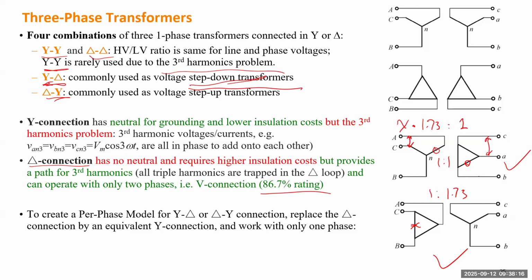So how are we going to do the calculation for a three-phase transformer? The approach is to replace any delta connection by an equivalent Y connection. Once you replace every delta by Y, you only pick a single phase of the Y, then do the calculation for a single-phase AC circuit. Because this course assumes steady state conditions, a balanced three-phase assumption holds for any problem. So we can calculate one phase and duplicate the result for the other two phases.